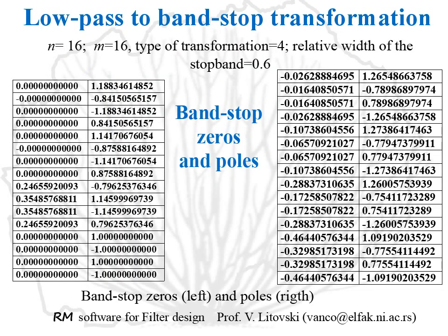Here is what the mapping creates. Everything doubles again. What is interesting here is that zeros at the central frequency of the suppressed band are created symmetrically, which is something specific to this transformation.